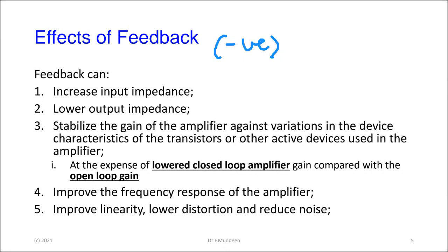You also want a low output impedance so that when you're driving a load, most of the output of the circuit, and in this case amplifiers specifically, will drop across the load and not across the output impedance of the device itself. In other words, you wouldn't waste your energy on the power of the system.